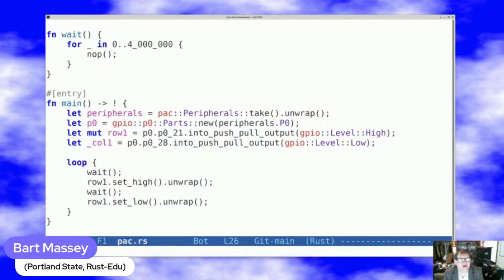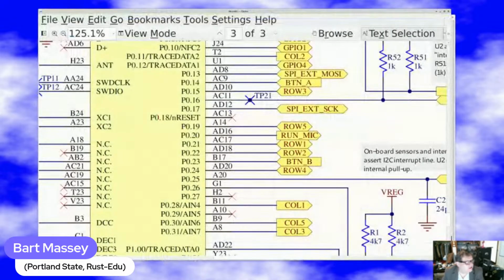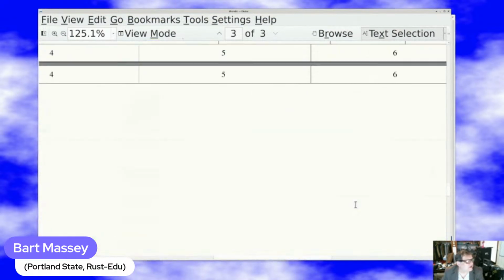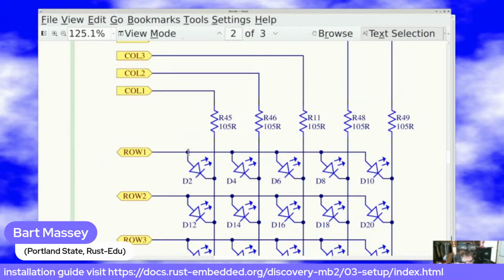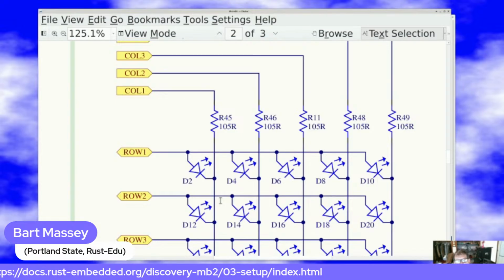And so we're okay. And then we'll wait another half second, and then we'll turn the row 1 pin to 0 volts. Let's go back up here. The col 1 pin is always going to be low. It's always going to accept electricity. It'll be ground. The row 1 pin will turn on for half a second, plus 3.3 volts. Then it will turn off for a second, 0 volts. When it's on, the electricity will flow through here and it'll light up. When it's off, electricity won't flow and it will go dark. And that's how we're going to blink the LED.